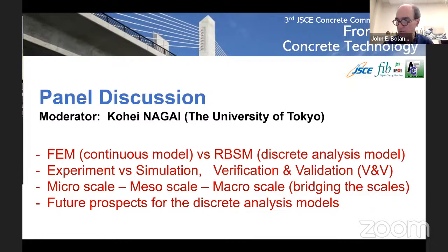We were looking at fatigue damage in macroporous concrete. After so many fatigue cycles, we stopped the test and impregnated the specimen with epoxy with fluorescent dye. So we could see the microcracks at different stages of development under fatigue failure.